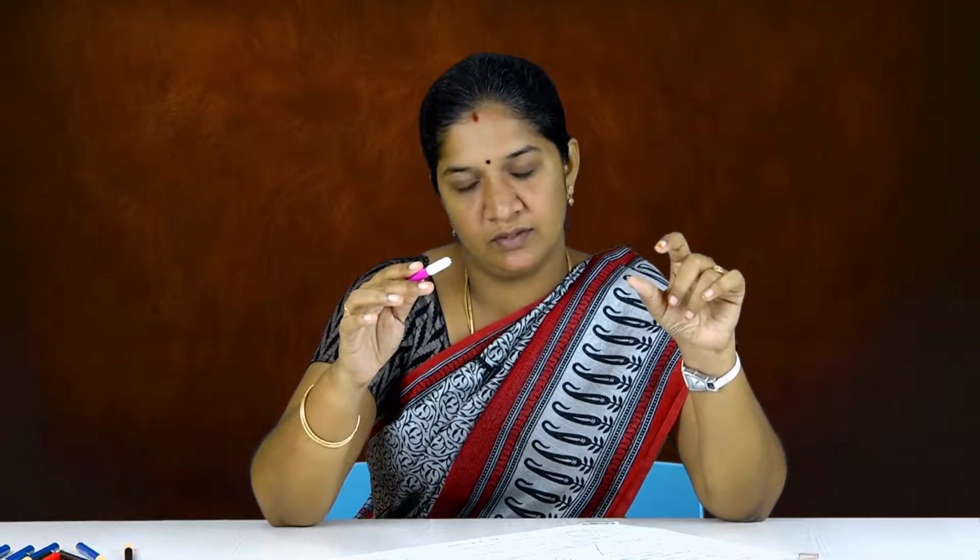That Mu limit depends upon the amount of steel you are providing in your section, based on your xu max by d, as given in IS 456, page number 70. We have some criteria: xu max by d changes depending upon the stress in your steel. For Fe 250, you have an xu max by d value of 0.53. For Fe 415 it is 0.48, and for Fe 500 it is 0.46.